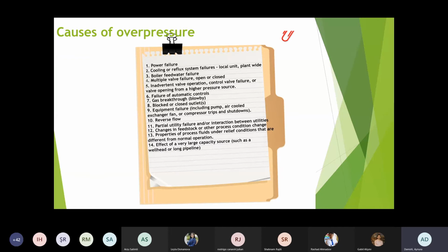So the high pressure, low pressure interface shall be considered between a large high pressure inventory that feeds a system of smaller capacity designed for lower pressure, for example, a subsea flow line or interfield pipeline feeding a topsides production manifold and separator.